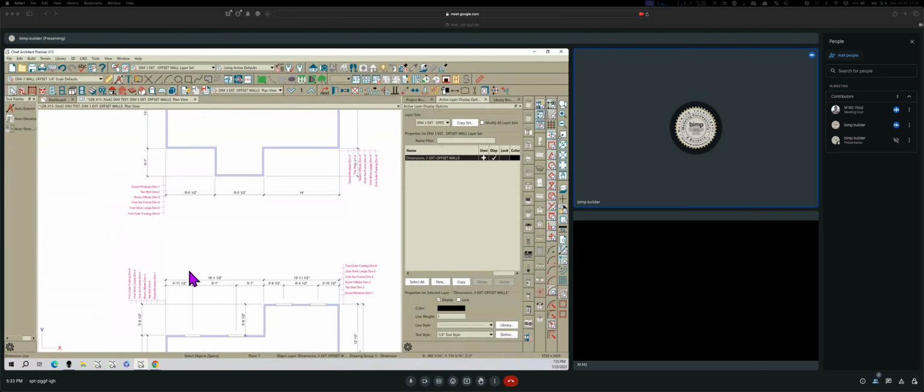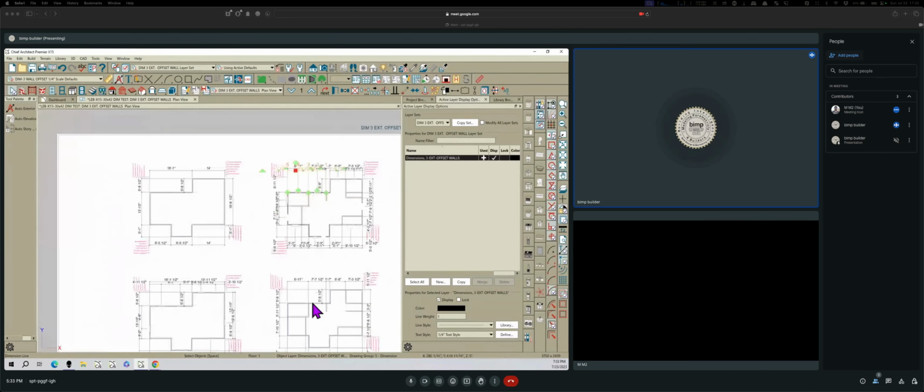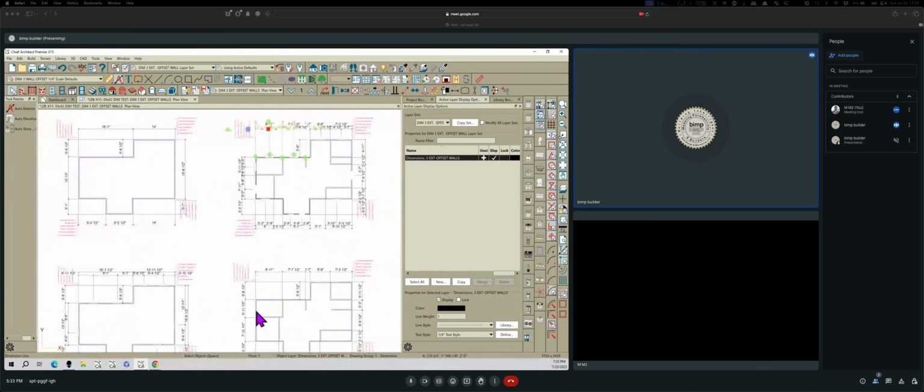And then when you get ready to do your T-walls, wherever they are, you're pulling that same tape from right there to that wall, to that wall, to that wall, and you're not picking your tape up and moving it like up here.